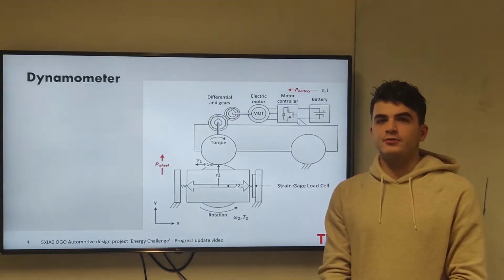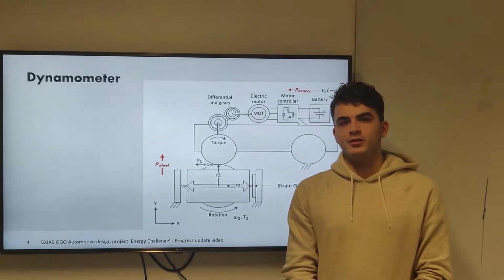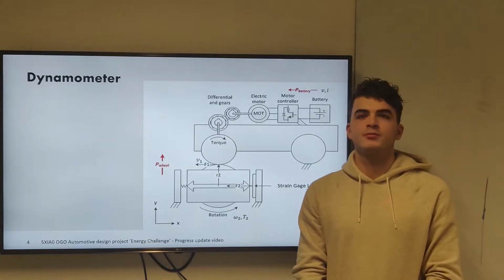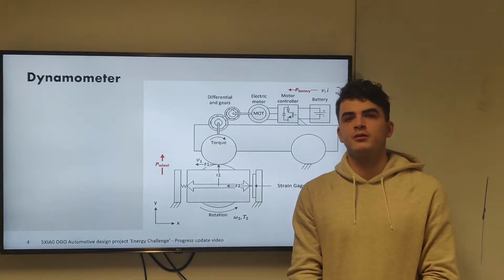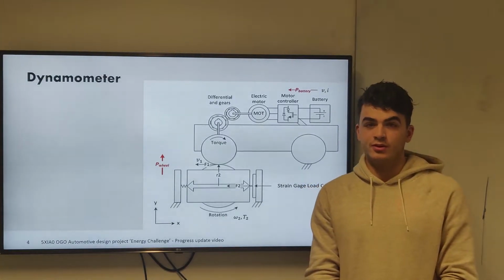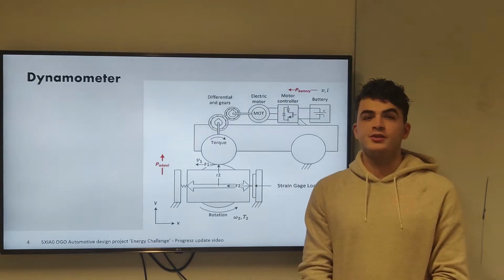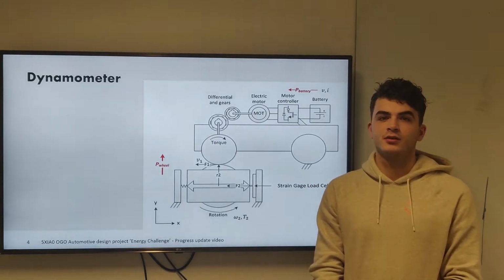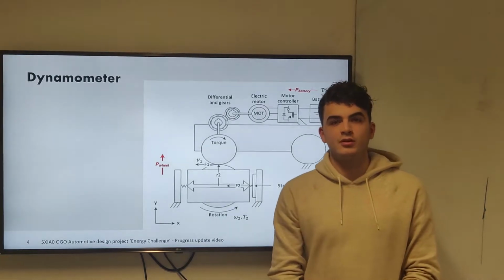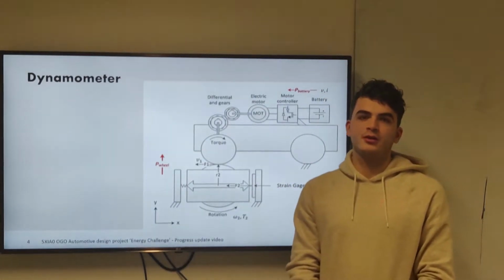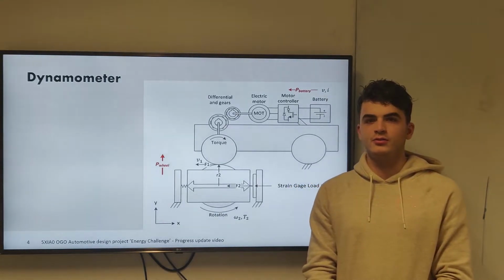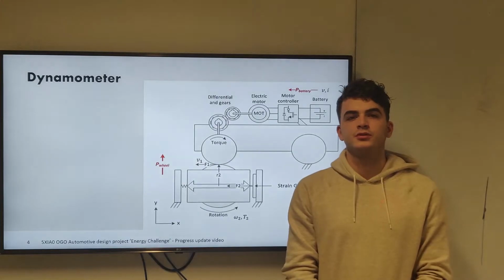The purpose of the first test is to create a formula of the power to the wheels. We need this formula because we can't measure the power to the wheels, but only the power of the motor of the dynamometer. This test has already been done for us, so we can focus on the rest of the test. From the values of test 1, it is possible to create a graph. From this graph you can conclude an equation that you need to calculate the powers on the wheels.